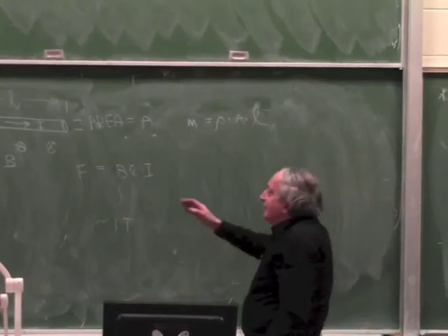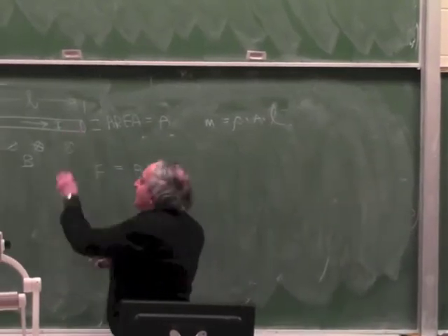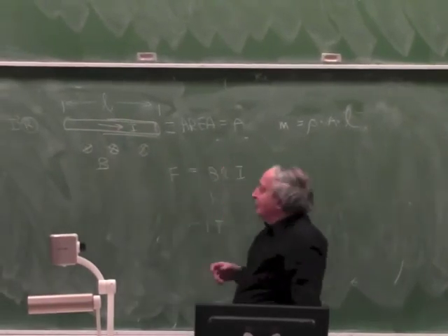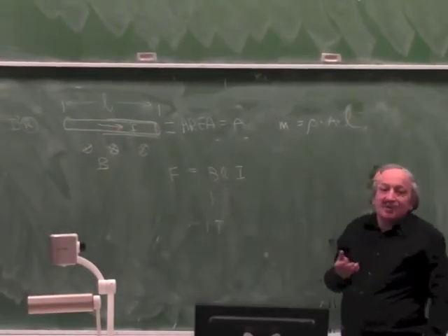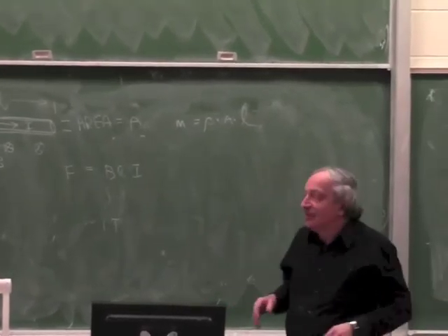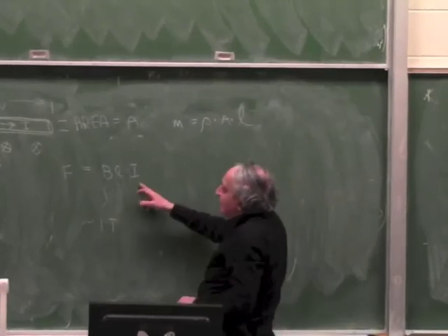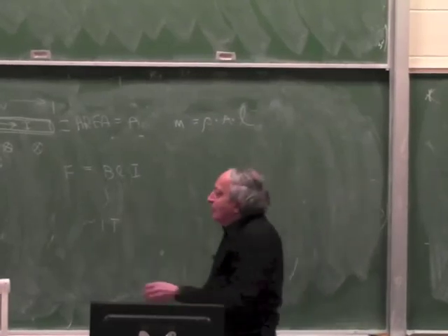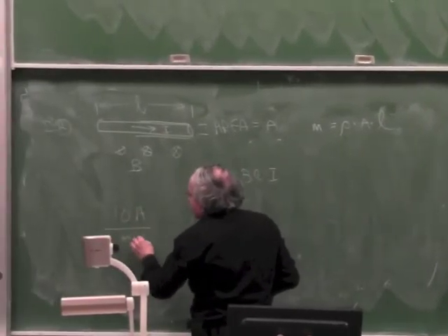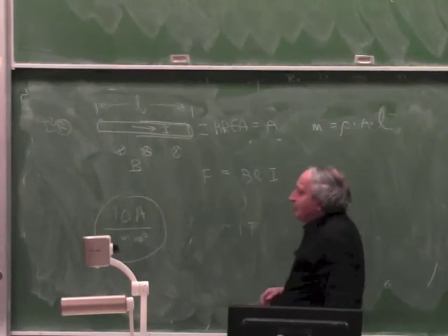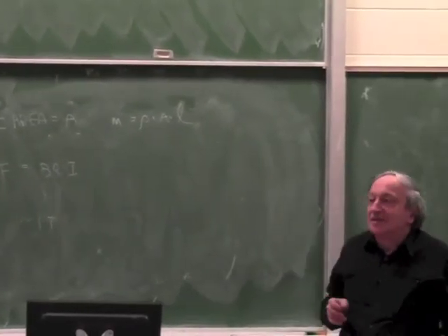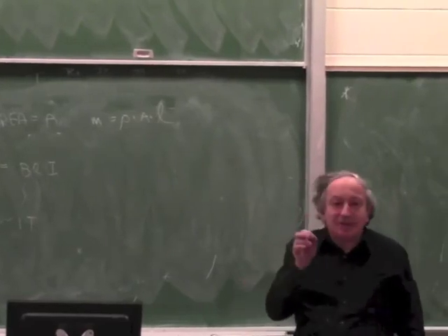And indeed, it's not a theoretical relationship, it's some rules of thumb. Because if the wire is heat resistant, let's say the wire has very good insulation, and I don't care if it heats up, of course I can run a bigger I through it. But a rule of thumb for all electromagnetic devices is that you don't want to run a current density of more than 10 amps per square millimeter.